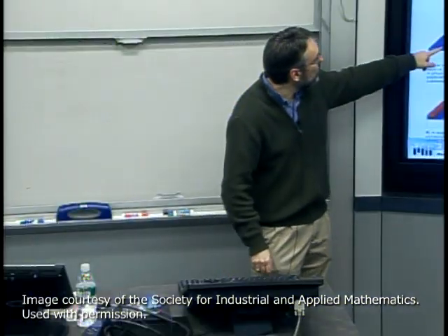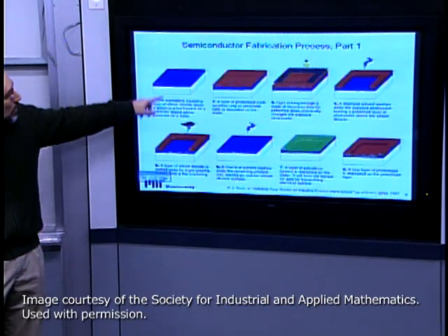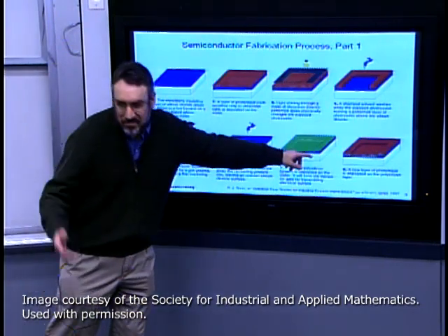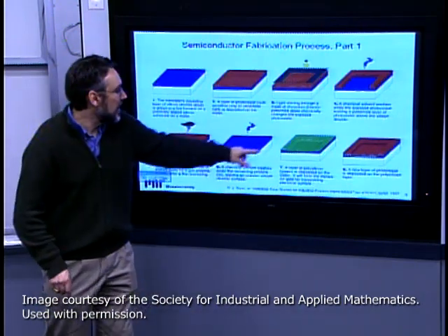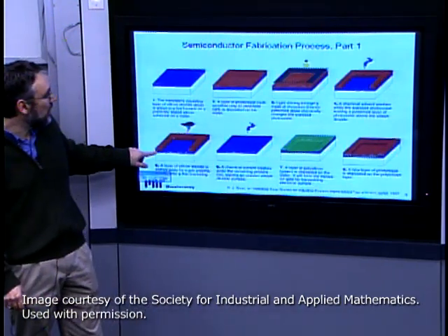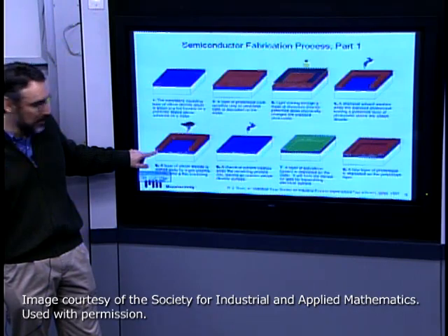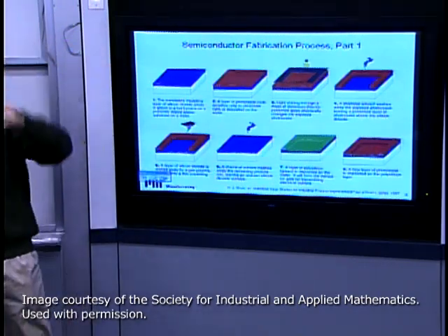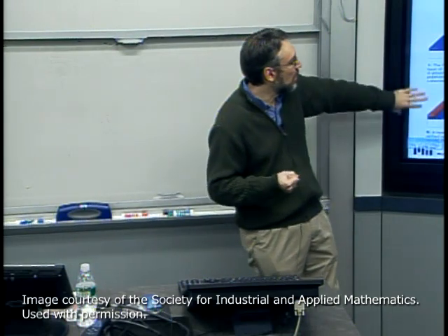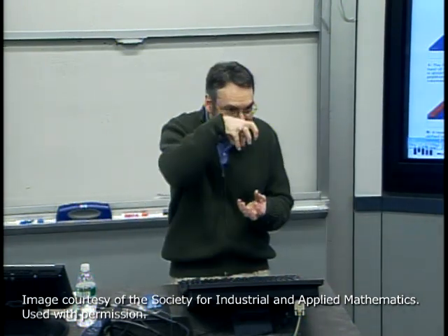So typically what you might have, close to modern technology, is a half a micron of silicon dioxide, fairly thick silicon dioxide, out here to act as a very, very big insulating layer, separating your metal electrodes from other components. But this silicon dioxide layer that's used between the gate and the semiconductor needs to be extremely thin.